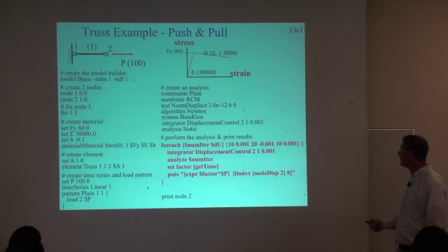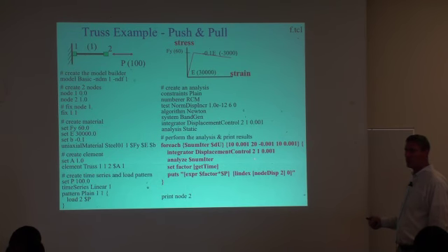We use displacement control. We control the displacement at node 2 in the 1 degree of freedom direction. At this point, 0.001 is a mistake. Hopefully the file will have the correct thing. This here should be the $delta u. So I'm going to construct the displacement controller every time, so that would be delta u. Then we want to analyze here. So we'll analyze 10. Second time in, I want to analyze 20. Third time in, I want to analyze 10.